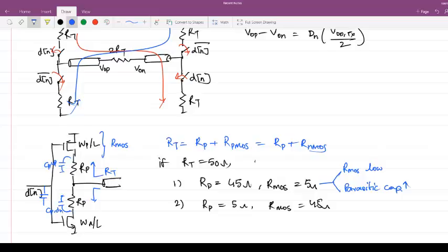If all the bits are 1, in that case your CP up has discharged whatever potential it could, whereas your CP down is completely at the lowest potential possible. Now as you switch between different bit patterns like 1010 or 1100, the CP discharge may not happen to the final value, and that introduces different crossing points, or different bit transition points, at the output.